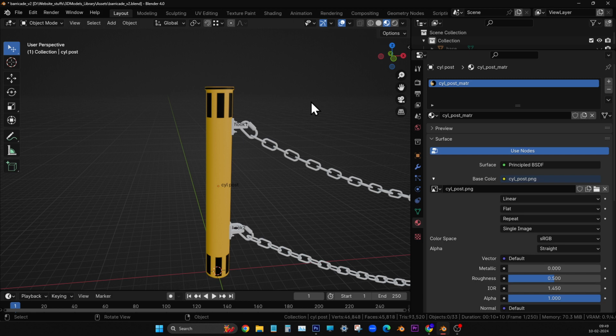Now you are seeing new and open buttons, right? No, not new. Open and give that texture. First one. Okay, right. Now you won't be able to see it because you are in solid mode, not in preview mode. So press Z on the keyboard and choose preview mode. Now you will see. Yeah, that's all.